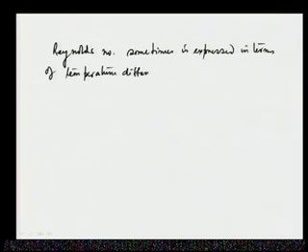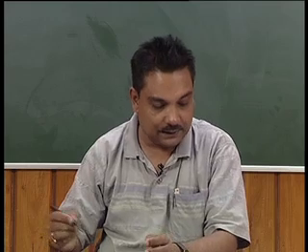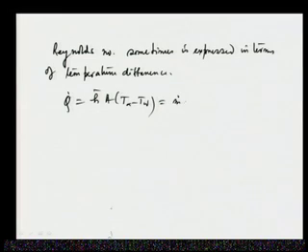So, we can understand that from the energy balance equations we can find out that Q dot, rate of heat transfer, is equal to h bar into area into T infinity minus T W, that is the convective heat loss, and that will be equal to m dot into L V, latent heat of vaporization. From there we can find out an expression for m dot. So, that is why m dot is replaced, this is equal to h bar by L V into area into T infinity minus T W.